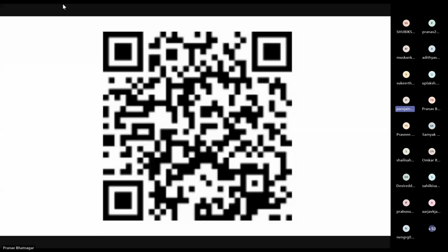How to assemble the part? Now I have reached it. Okay, so on the top there's an assemble menu, right? Next to the modify one. Yes. Go click on that. Click on the drop down. There's a joint option. Click on that, and then click on the outer bottom edge of the cap.